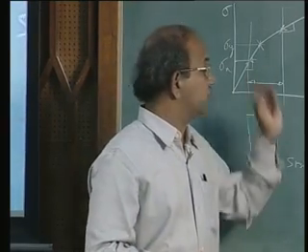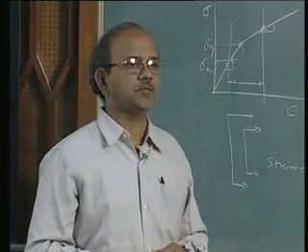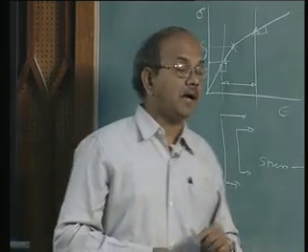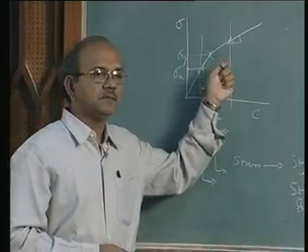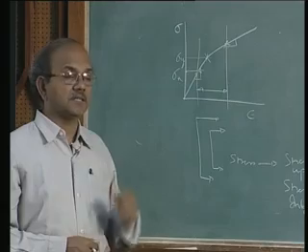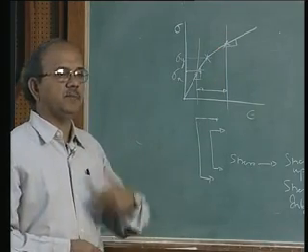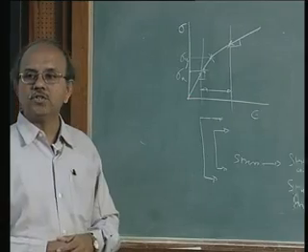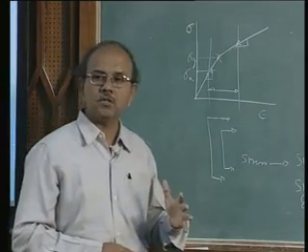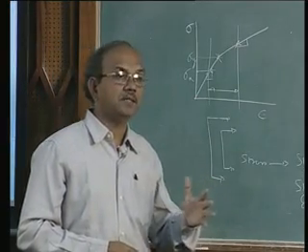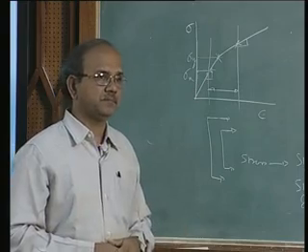Now, what are the other issues? There are other issues as well. I have to calculate the stress such that it lies on the stress strain curve. In a multi-axial case, this means the stress would lie at the yield surface.